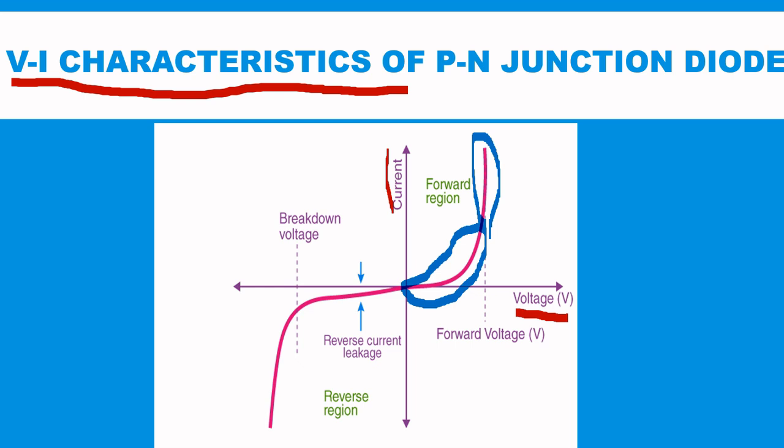When the PN junction diode is in reverse bias condition, means P type is connected to the negative terminal and N type is connected to the positive terminal of external voltage. This results in an increase in potential barrier. Reverse saturation current will flow in the beginning as minority charge carriers are present in the junction.